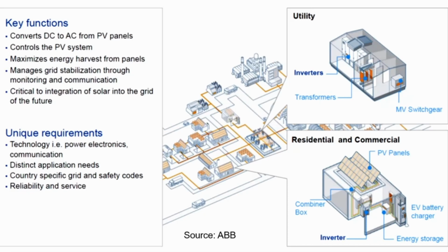This is different in different countries. Usually in Germany we have 150 milliseconds, so for 150 milliseconds you have to keep the power on the system. Italy, for example, I think it's longer, almost half a second, and so on. This should be homogenized. It's already on the way in the European Union, so we will have a homogenized system there.